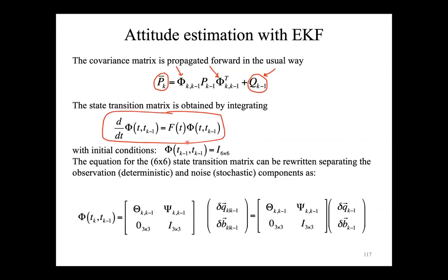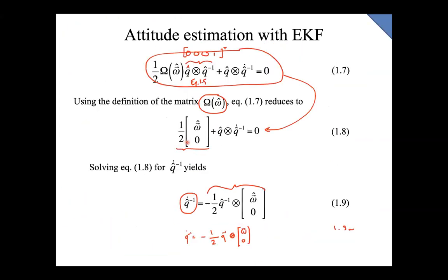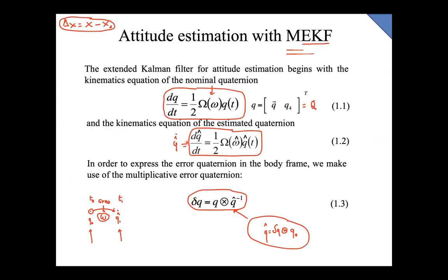Well, just to clarify, the first part of the demonstration is only related to the propagation of the errors. So this delta Q corresponds to the error associated to the quaternion between the reconstructed attitude and the real trajectory. Here it is assumed that you know the real quaternion.